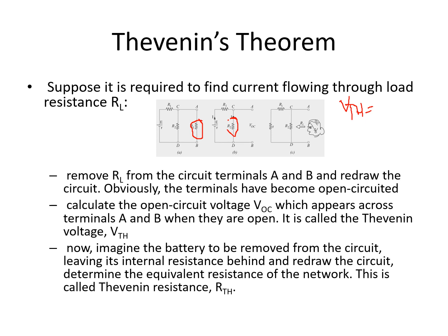So using the voltage divider principle, we can determine our VTH as your source, which is E, multiplied by your R2, divided by the total resistance, which is R plus R1 plus R2. So we now have our VTH.